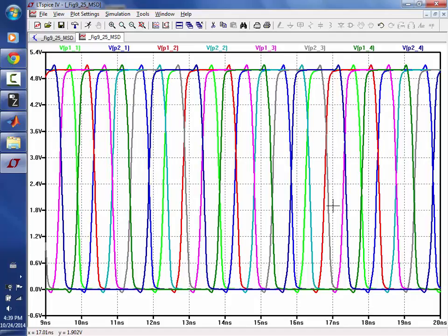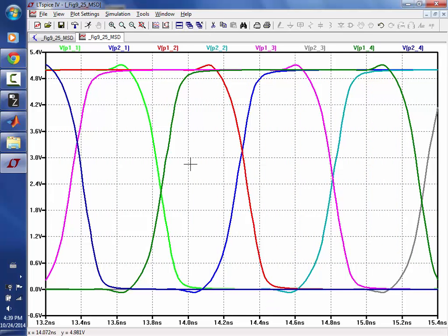Does everybody see that? Now, keep in mind also the effective sampling frequencies, the distance between the rising edges. And this is an old process, and this distance is roughly 500 picoseconds or 2 gigahertz. So even in this old process, you're able to do gigahertz level sampling. It's pretty significant. Does everybody follow that?